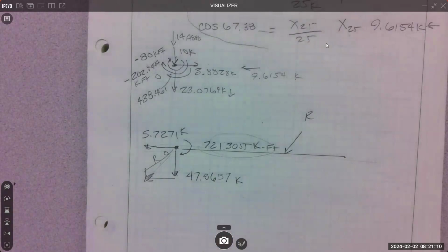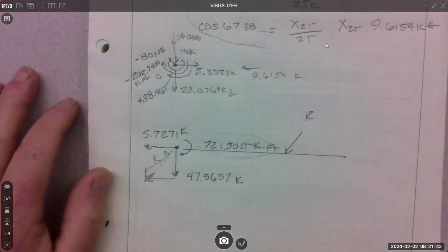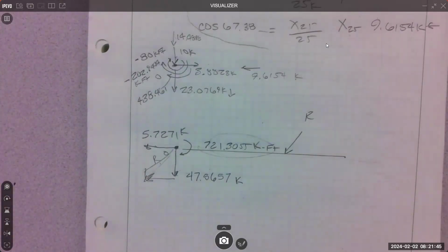In previous ones, we've just left it going through the point? Yeah, no, the last couple problems, we started moving the resultant out onto the beam. Because it's really out somewhere on the beam. We get the resultant because we have these two magnitudes, we can do Pythagorean theorem, we know the magnitude of the resultant. We just don't know where it is. And it's not here because of this moment. If there was no moment for some reason, then it must be right there, not creating a moment, right? But since there is a leftover moment here, that means R is out there somewhere. And we have to find out where it is.